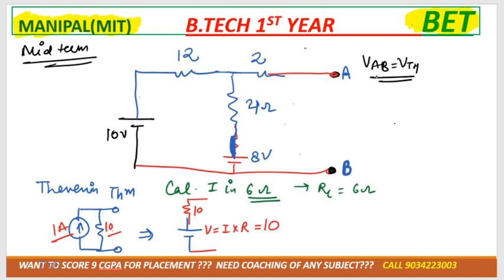Now we need to calculate VAB, right? Where are you standing? At A. Where do you have to go? To B. Suppose this is C. Point between, always mark the point between resistor and battery. Okay? This is D. This is E. So VAB is how much? VAC plus VCD plus VDE plus VEB. Okay? AC is open circuit.